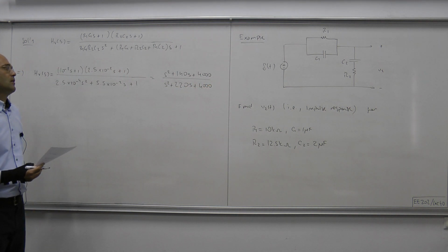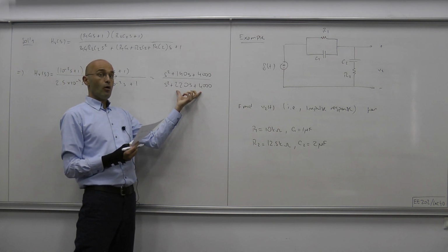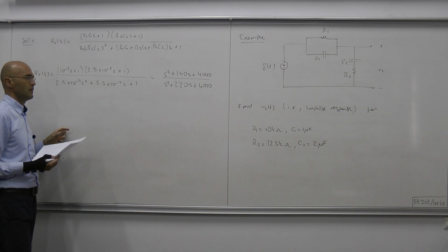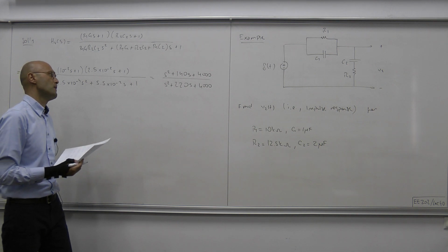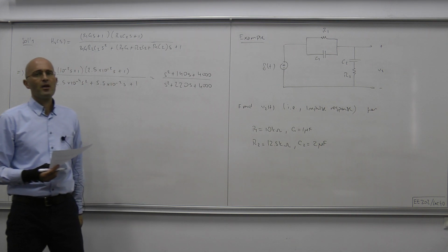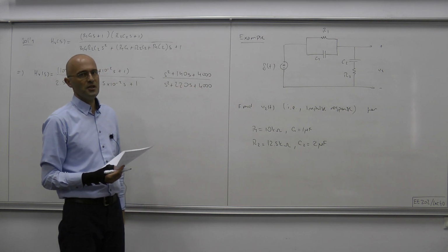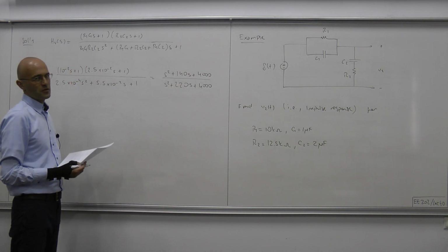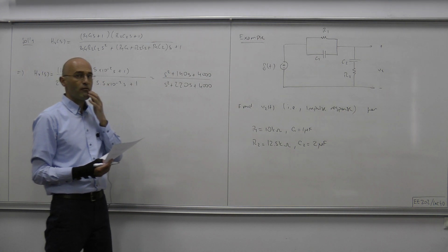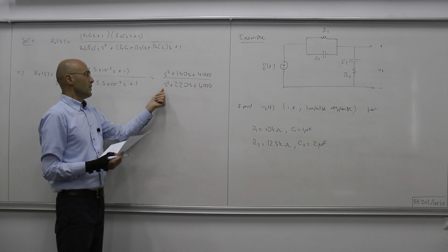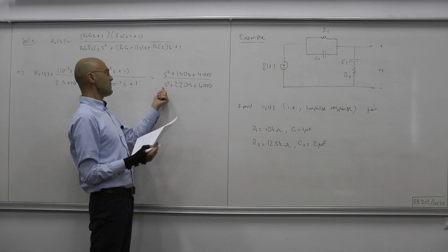Now, what we're going to do is find the poles of the transfer function, or the roots of the denominator polynomial, and then apply partial fraction expansion and write it as first order terms, and then it's easy to figure out the inverse Laplace transform. We cannot directly write this as a sum of first order terms, because this is not a strictly proper rational function.